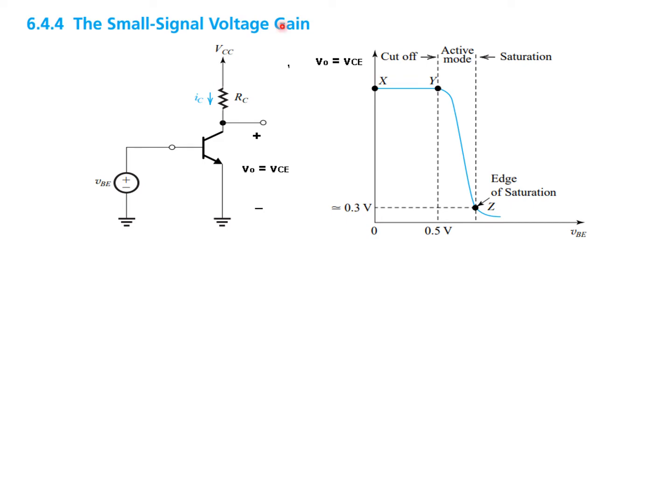Now, the small signal voltage gain will be operating here, and one point I would like to emphasize: this you can see is small v, then capital VBE. That means this has actually two inputs. One is the DC, which is VBE all capital, and with that is AC, which is vbe all small, and the sum of the two is the small v capital VBE.